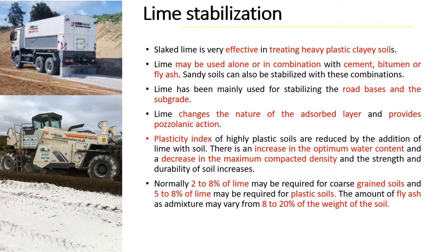Lime-treated soil is more suitable for warm regions where the temperature is very high, and for colder regions it is not very suitable. Lime soil stabilization is suitable for soils like clay, silty clay, clayey gravel, and others, and it is not suitable for granular soil or sandy soil.